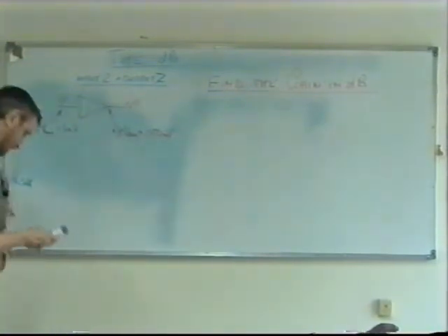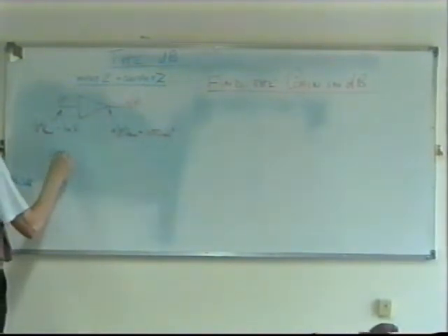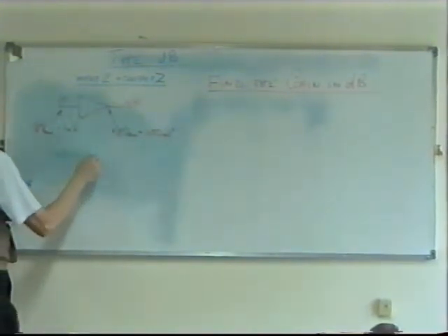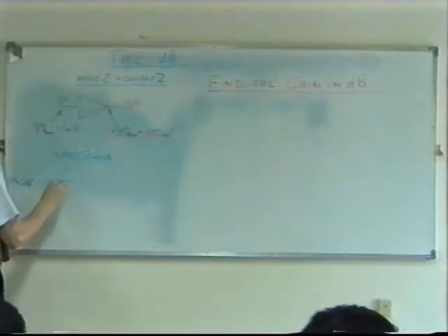Yes, that's right. So again, we're going to use the same formula of power ratios, because that's what decibels are: power ratios, not voltage ratios. To find the input power for this amplifier, it's equal to V squared divided by the impedance, V squared over R if we assume it's a resistance.